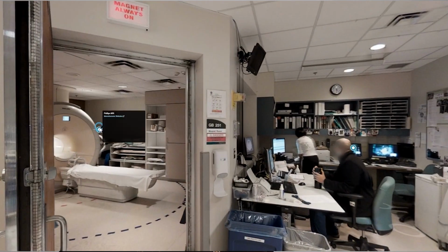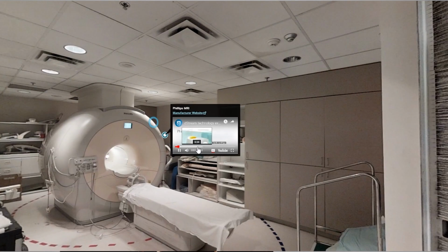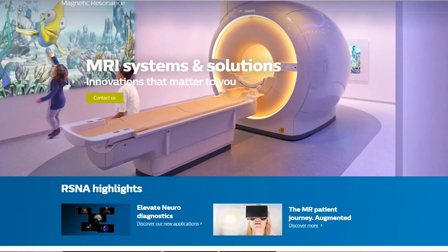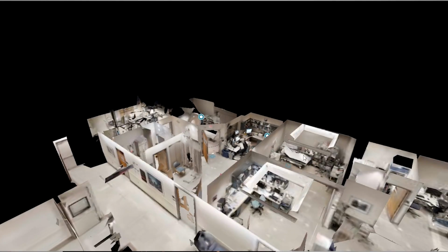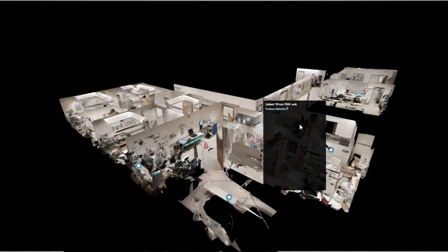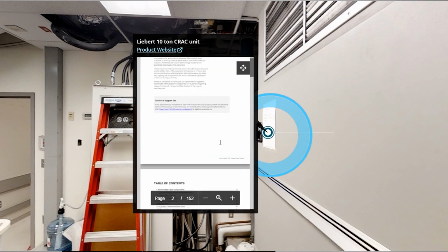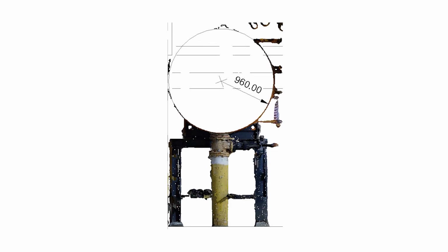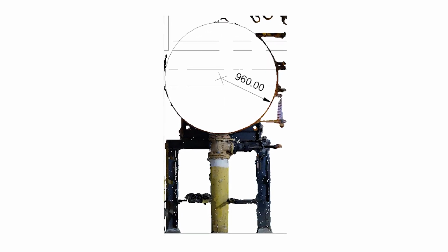The Matterport tags were an integral part of our Revit family creation process. I would identify the equipment using the online site walkthrough, get equipment sizes, get measurements for that equipment in the workshop mode, create the Revit families, and then I would use Matterport tags to tag that equipment in the Matterport cloud with the Revit family name and the family type, so that the designers can access that live link fully updated and have all of their information in one central up-to-date location.